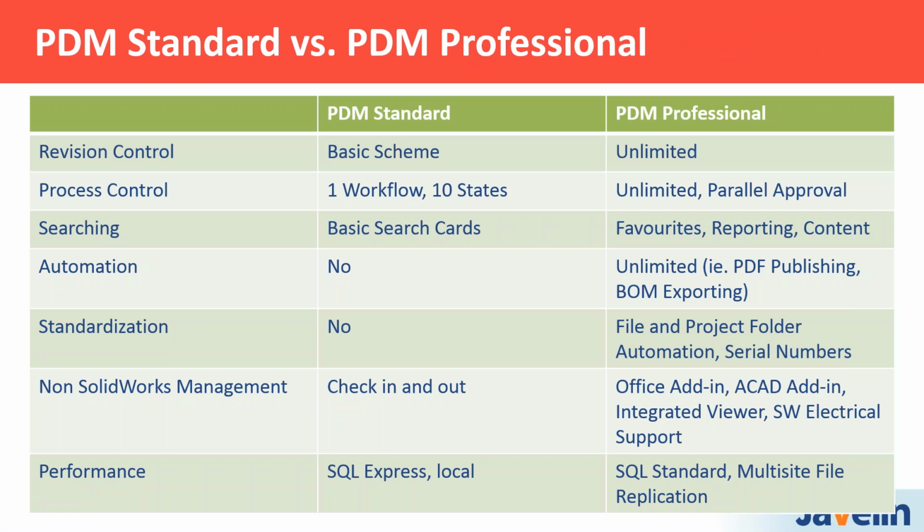Wanted to summarize just a few differences between PDM Standard and PDM Pro, just so we get that out there. The biggest reasons I see are right in the middle there, related to automation and standardization. So PDM Pro, based on workflow, can publish bill of materials, publish PDF drawings, and do a lot of automation in the back end. As well as automation of email notifications, and so there's lots of things to streamline your processes further and make them faster, and also standardizing.